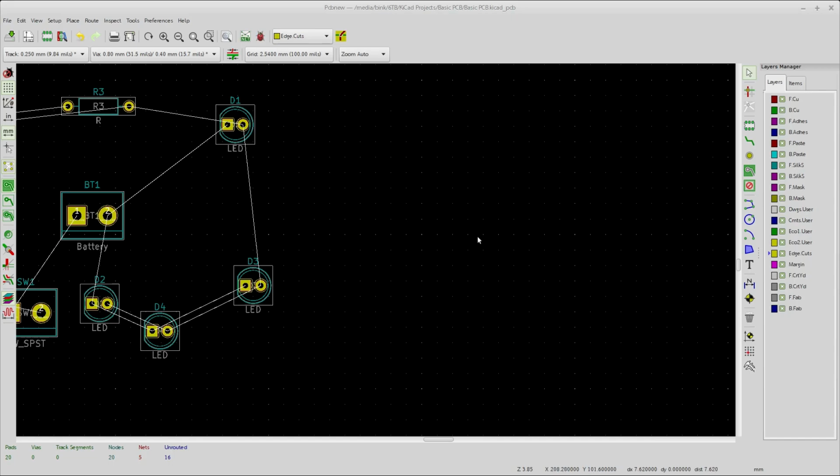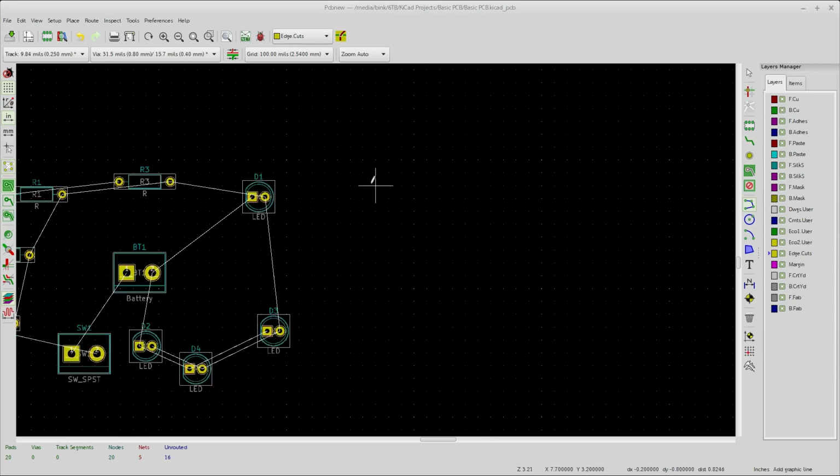So what we're going to do is you're going to pick, again, your edge cuts over here, and then you're going to say graphic lines. So you pick this, and now it will snap to the grid lines. You will also want to come over here, since we're thinking inches for right now, set the units to inches here. Now, come out here somewhere. It doesn't really matter. You might zoom in and out to make sure that you actually have enough space to do this in. So I'm going to come up here to just, I don't know, that dot there because it's more on the bold line.